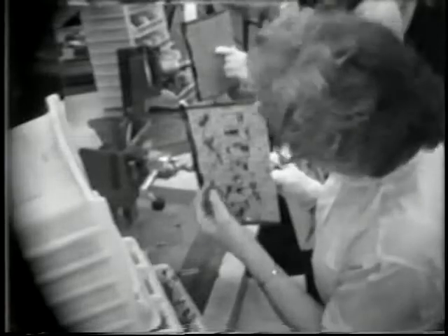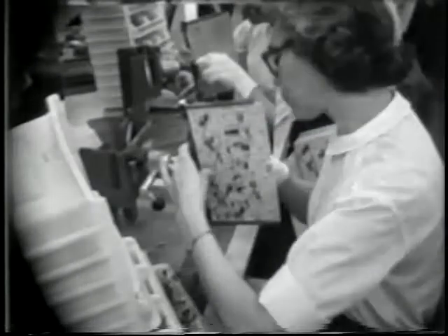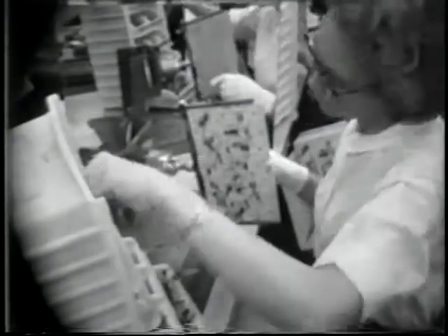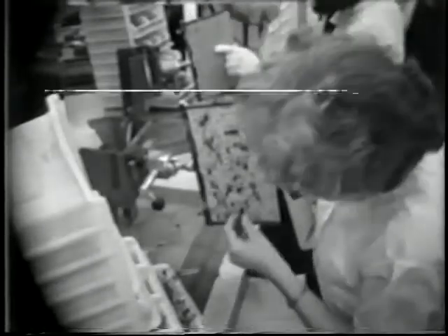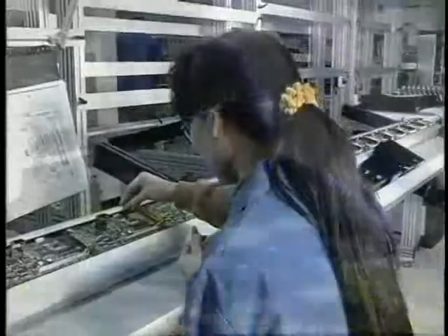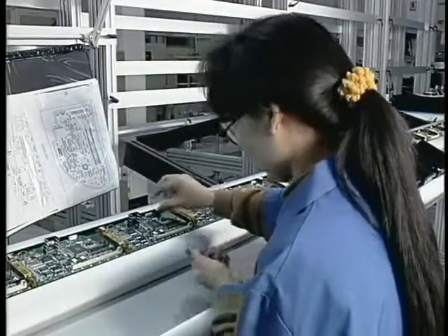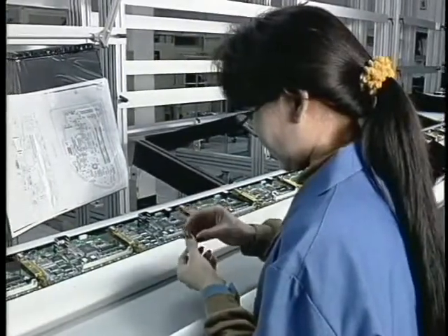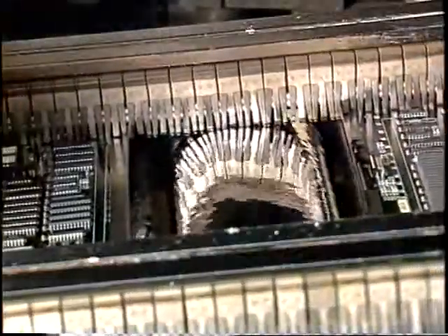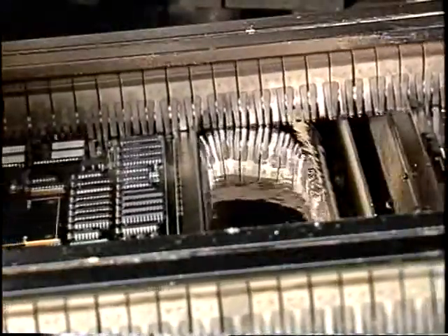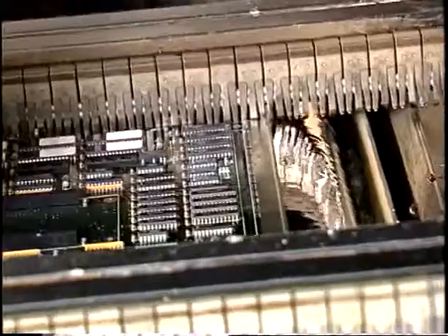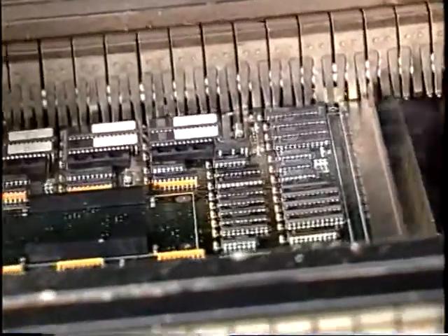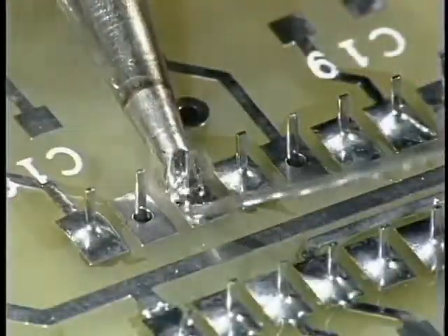The component leads were inserted into the holes of a printed wiring board and joined with solder to form an electrical connection. Today, adding the components to the board can be done very quickly by automatic insertion machines. Or they can still be done by hand at manual assembly stations. And the soldering of the component leads to the board can be performed by passing the entire assembly over a wave of molten solder or manually with a soldering iron.